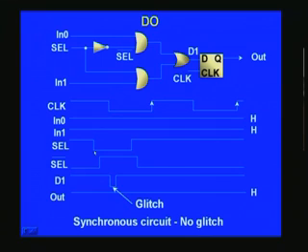So here, of course, there is a delay, and this gate delay is because of this inverter here. If you see the output here at D1, what happened? It is nothing but ORing of this, since IN0 and IN are 1 each. So whatever you apply here, that is select bar here and select here, will appear at the respective ends here, and when ORed you get basically this, it's precisely this rather,